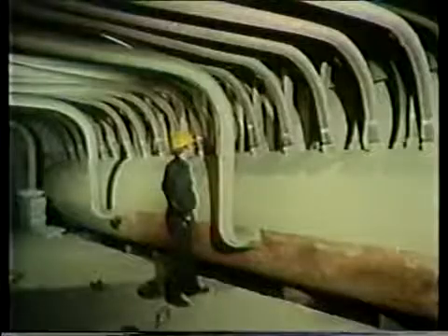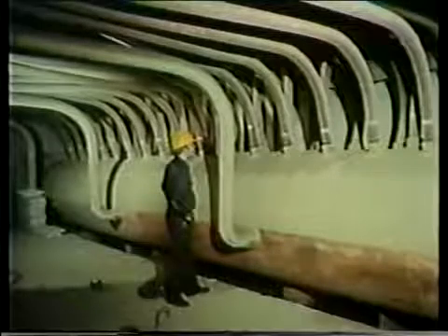They may be flat metal plates across the downcomer opening, or they may be a sleeve that extends the downcomer into the drum. In all 3 types, make sure the baffles are firmly attached and that the plates or sleeves are not cracked. In a drum-type boiler, there are hundreds of tubes connected to the drum. Each attachment should be inspected for corrosion, cracks, and erosion.